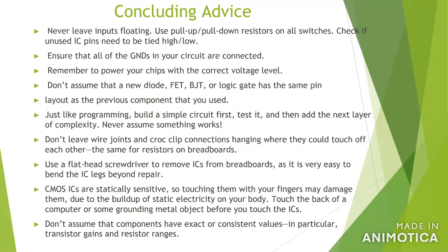Never leave the circuit open. For example, for our project, you use a Raspberry Pi, and the Raspberry Pi I gave you is an open circuit board. That means before you power your Raspberry Pi, you have to make sure that there is no metal on your table. If you have metal, that will short the Raspberry Pi and burn it, so you want to avoid that.